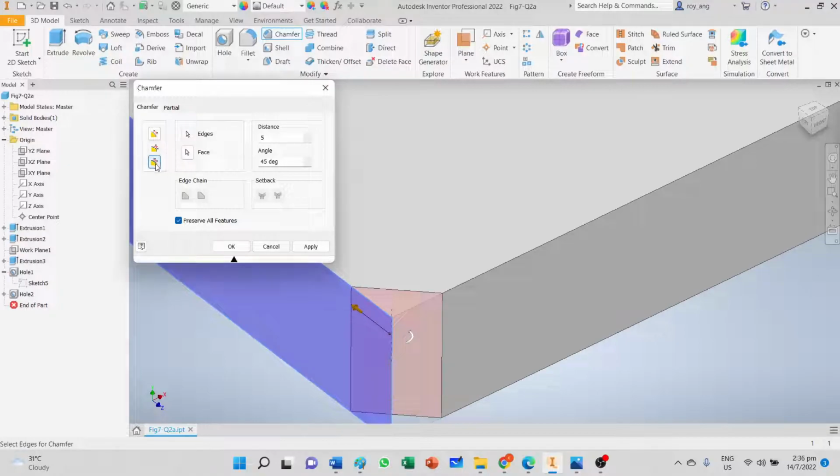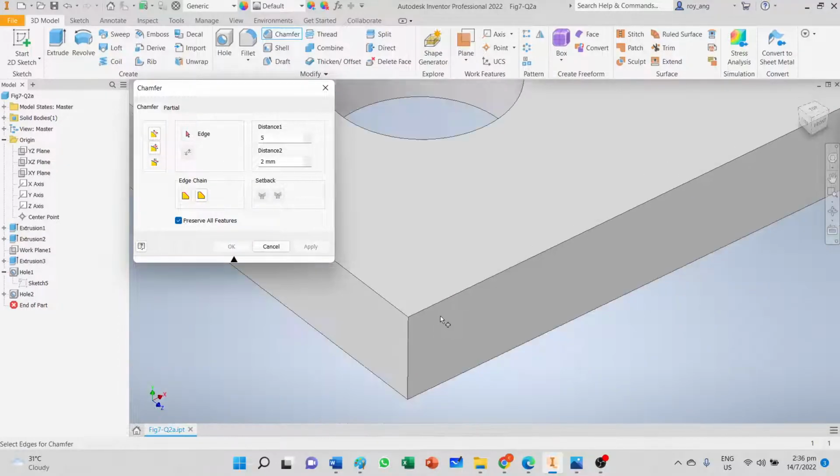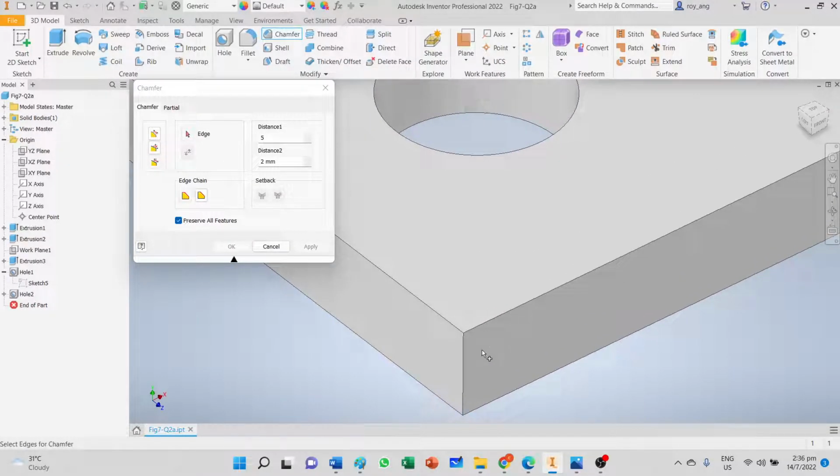So sometimes you want to create, like this particular example, a chamfer that has got uneven distances from the corner, and this time around what I'll do is that I will put the first number as 25, okay, and then I will click it over here, and then I can clearly see that this is the distance that is 25 and this is the distance that is 2, and I can ask myself, oh, is this the correct orientation? So this is not the correct orientation.